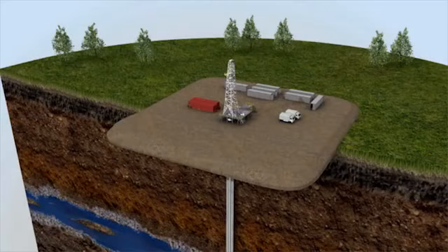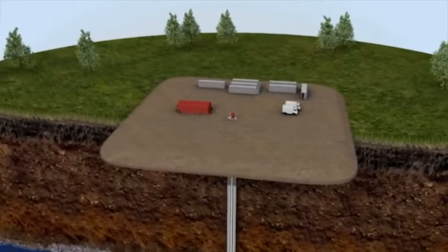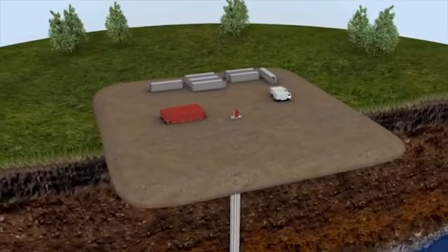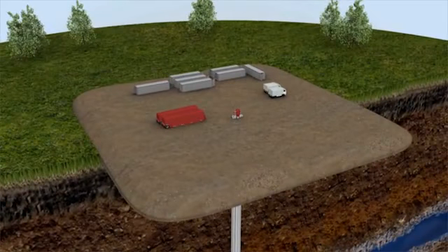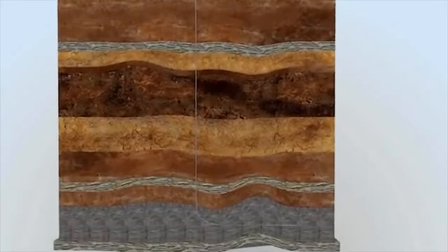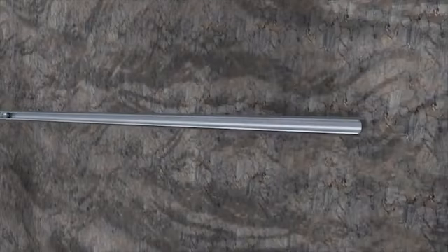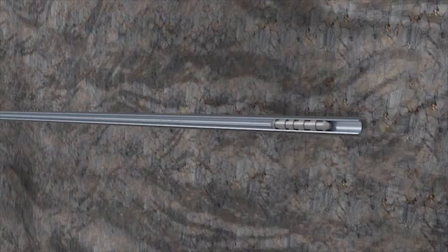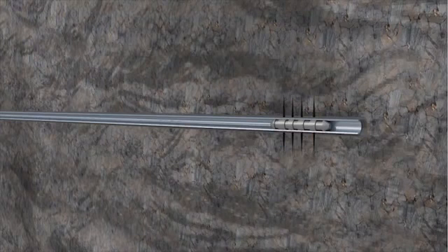Once the drilling is finished and the final casing has been installed, the drilling rig is removed and preparations are made for the next steps, well completion. The first step in completing a well is the creation of a connection between the final casing and the reservoir rock. This consists of lowering a specialized tool called a perforating gun, which is equipped with shaped explosive charges, down to the rock layer containing oil or natural gas. This perforating gun is then fired, which creates holes through the casing, cement, and into the target rock. These perforating holes connect the reservoir and the wellbore.